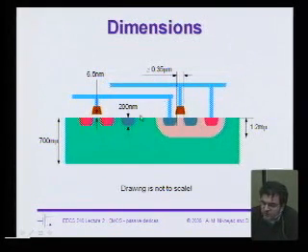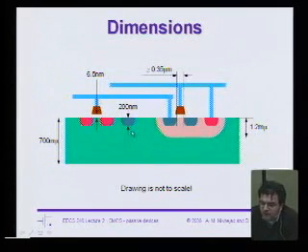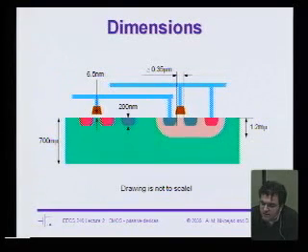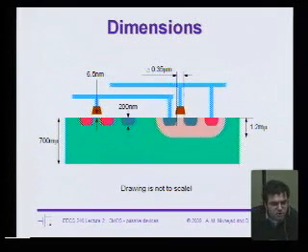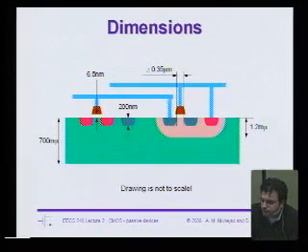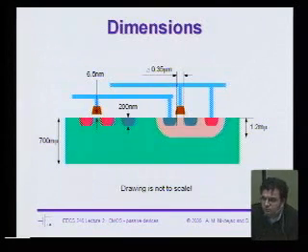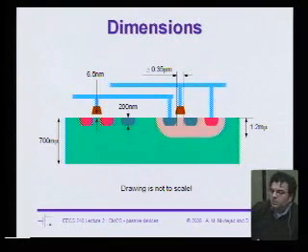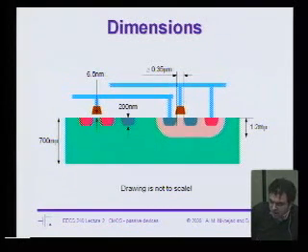The junctions, as you'll notice here, the junctions have gotten very thin, even thinner than this in our process. And that actually is not necessarily good for the transistor. Why is it that thin junctions are used? And two, why is that bad for us? Less short channel effect using thin junctions, and it's bad because of increased series resistance. Exactly, yeah, right on the money.